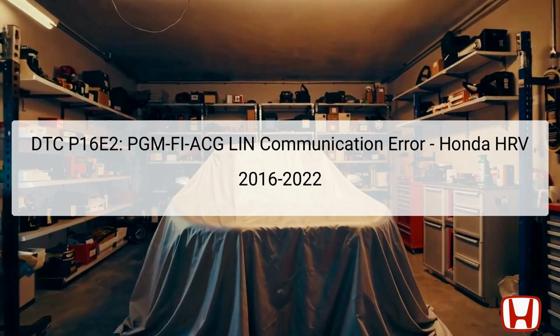The DTC Diagnostic Trouble Code P16E2 signifies a PGM-FI-ACG LIN communication error in Honda HRV models from 2016 to 2022. This error indicates that there is a communication failure within the LIN, local interconnect network, related to the Powertrain Control Module, PCM, and the alternator.